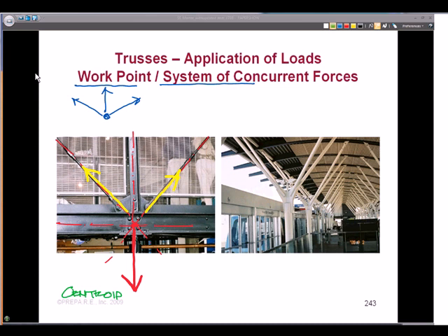Okay, let's imagine if this threaded rod ended up connecting right here on this member. Okay, so as it came down and was connected, if this load pulled down and this was pulling up in resistance, now we have two equal and opposite forces separated by a distance, and it starts to bend this member and we get bending in the connection. So concurrent forces eliminate the bending.